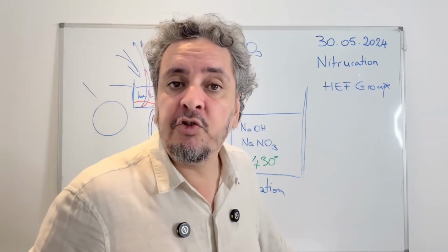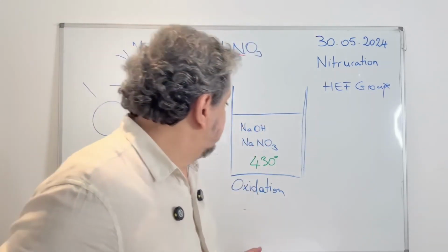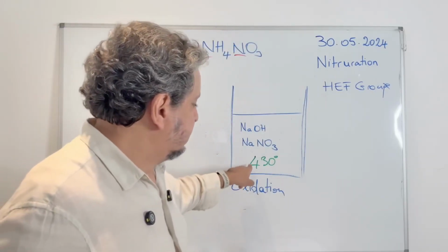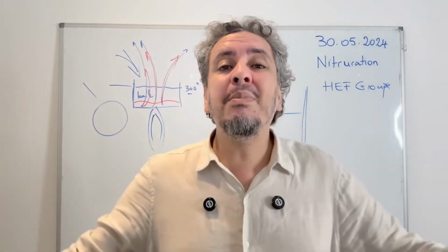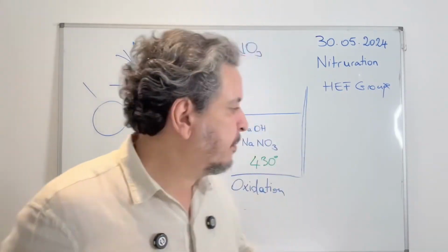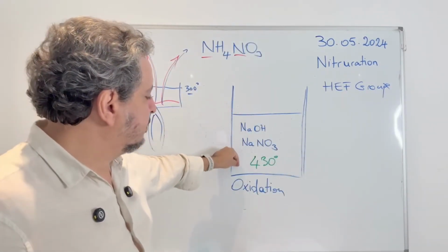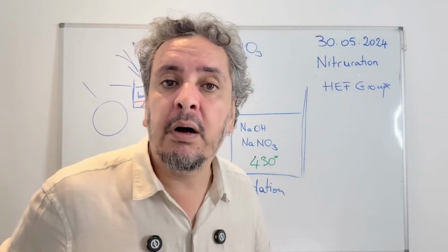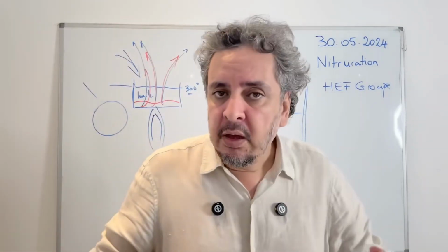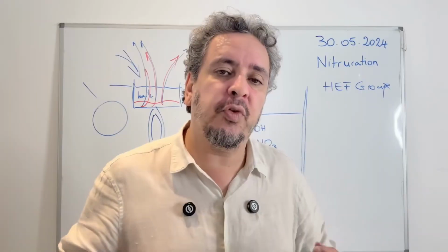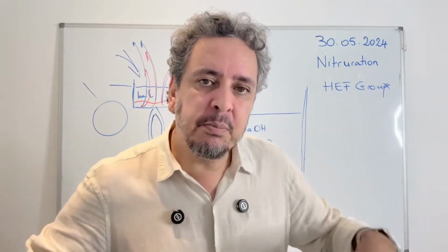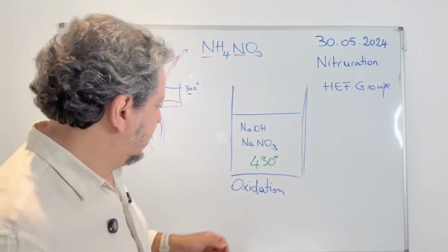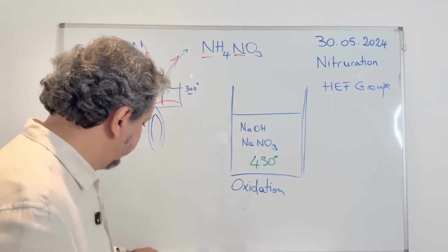So what does he tell them? The process engineer tells them, in this case, the only way to melt this salt blockage is to put the tubes back in the basket and lower them back in there. You put them back in the bath for a few minutes, and you wait to see what happens as it heats up. And then the salt plug will come off. After that, you take it out again and let it drain well, okay? They will follow these instructions.